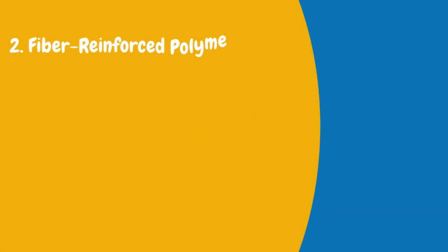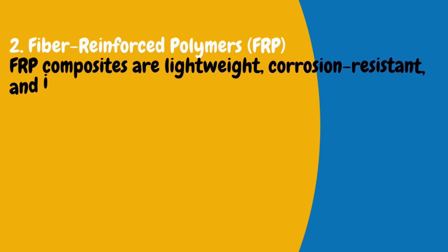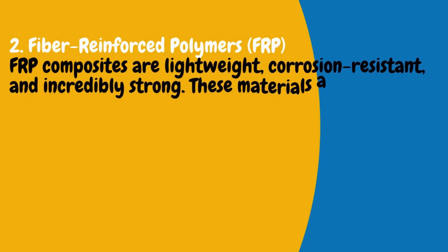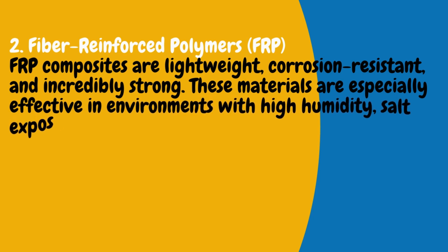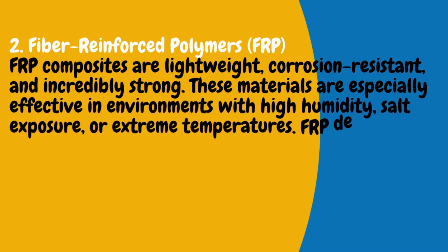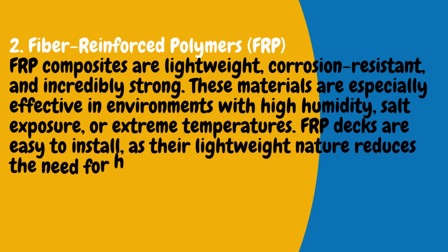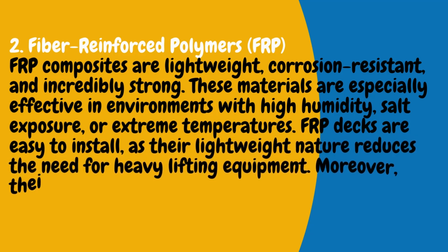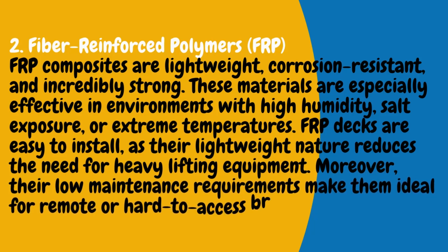2. Fiber-reinforced polymers (FRP). FRP composites are lightweight, corrosion-resistant, and incredibly strong. These materials are especially effective in environments with high humidity, salt exposure, or extreme temperatures. FRP decks are easy to install, as their lightweight nature reduces the need for heavy lifting equipment. Moreover, their low maintenance requirements make them ideal for remote or hard-to-access bridges. 3.